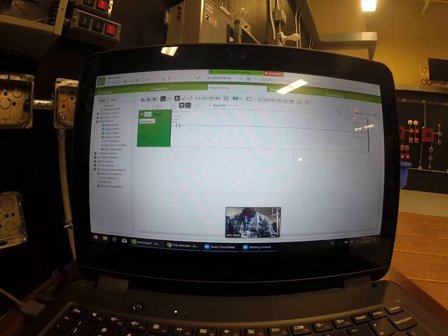Now that's good, and if you look at the top of your screen, there is no longer an error. So that's telling us that this program is ready to run or simulate. It's pretty happy with what it sees. Bring your mouse all the way to the top of the page, right next to the no error symbol, and you're going to see Launch Simulator. Click on that.